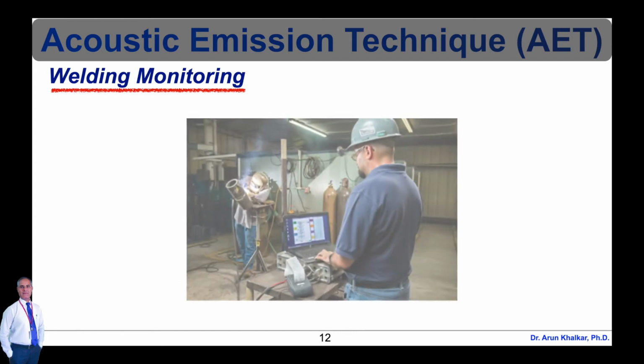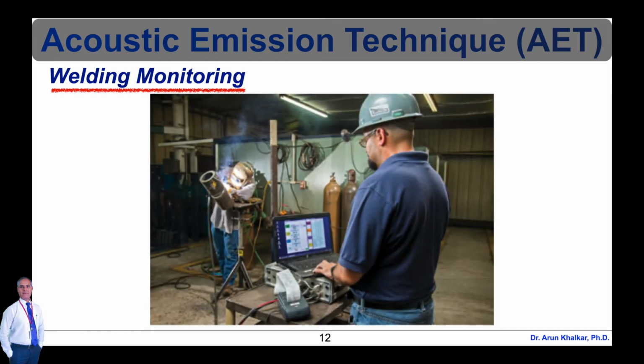First of all, welding monitoring. During the welding process, temperature changes induce stresses between the weld and the base metal. These stresses are often relieved by heat treating the weld. However, in some cases, tempering the weld is not possible and minor cracking occurs. Amazingly, cracking can continue for up to 10 days after the weld has been completed.